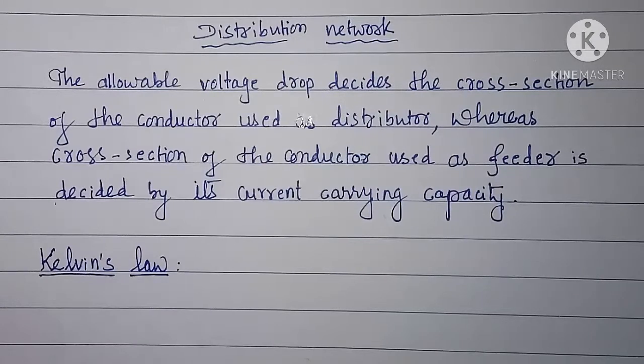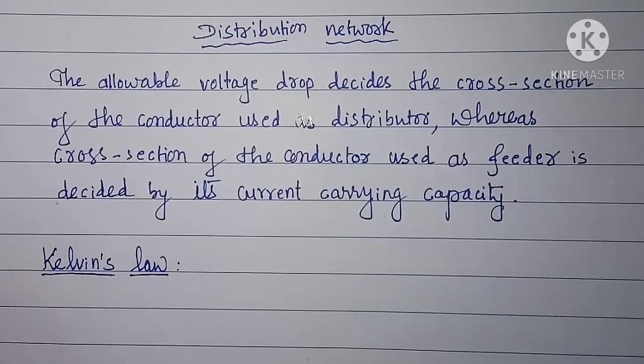Now, our aim is to determine the economical size of the conductor used as a feeder. For that, we make use of Kelvin's law.